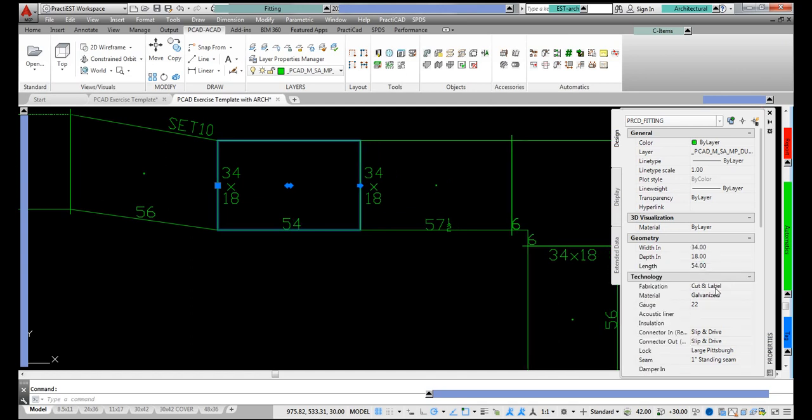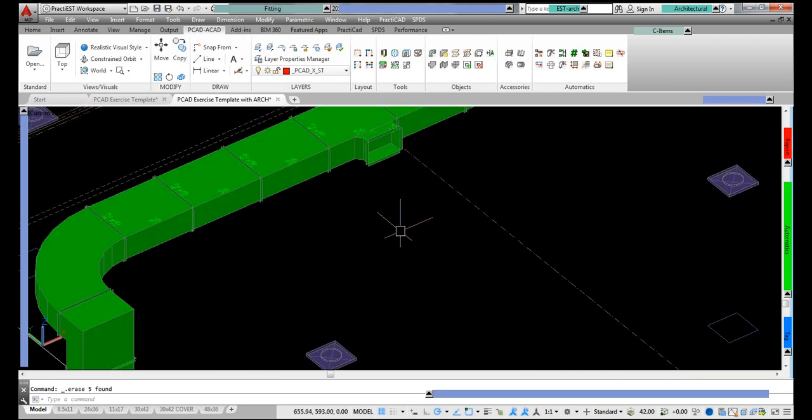Following that, we will change the connections, and you can see it's adjusting connectors of surrounding fittings and also adjusting length. If we bring everything back to what should be a coil line piece, PractiCAD will automatically update it again. By specifying your criteria for what fitting should go to what machine, we can completely automate the download to PractiCAD. So let's cover the workflow for drawing duct again.